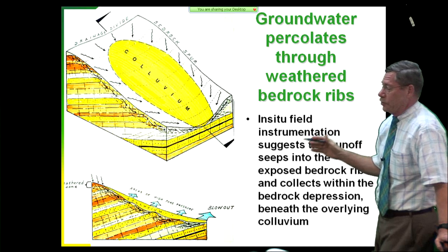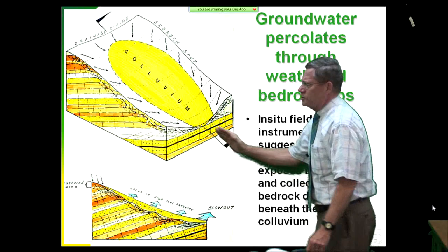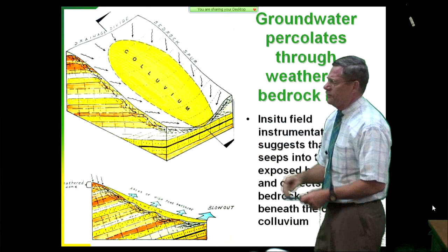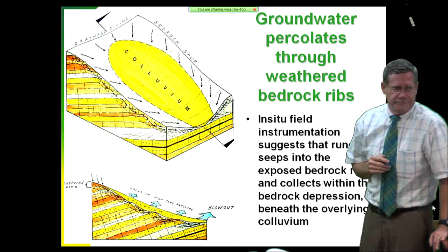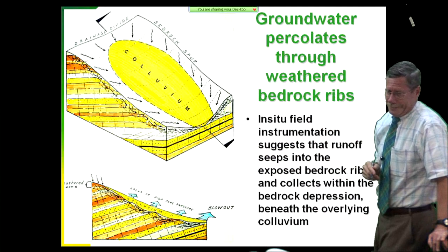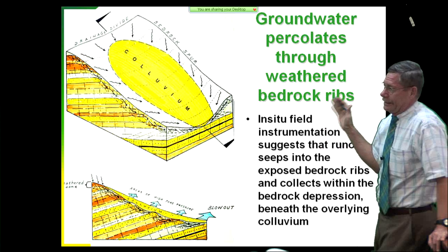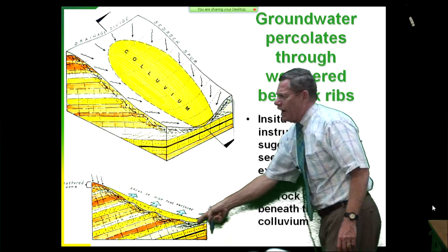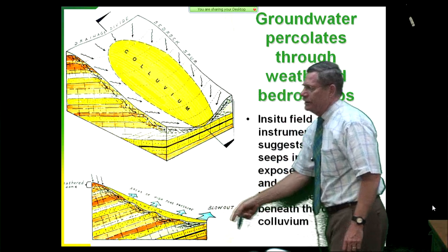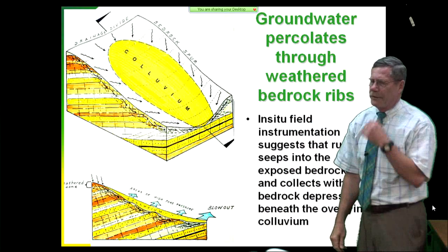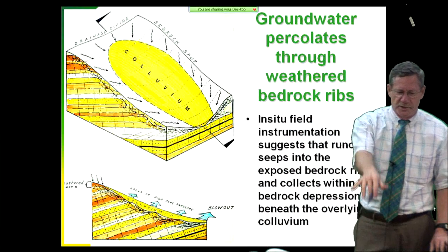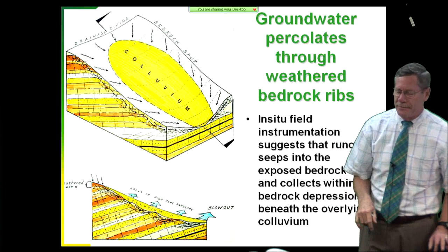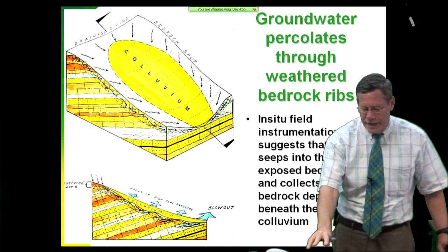Because you can put in the trench drain right here cheaper than one phone call to Shannon and Wilson. So you might as well just go out and do it, because you have plenty of rock, and you just want to get some drainage in there so that you alleviate high pore pressures building up. And you'll figure it out pretty quick when you put those in, because you'll hit water at very shallow depth when you go in there and dig around with the backhoe.